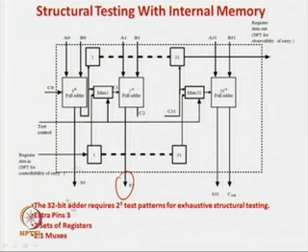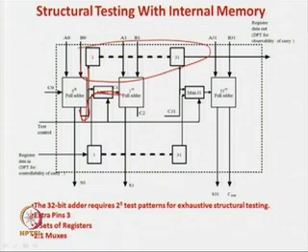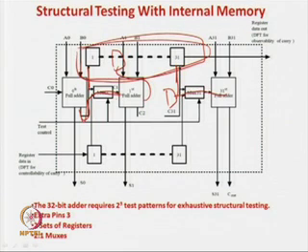In this case people have applied a very simple logic. We have a simple shift register. What do you do? The intermediate carry output of this gate is feeding this. For the time being, forget about the multiplexer, this is being fed to the next level of the adder, and also the same thing is written to a shift register. Again there will be another element of the shift register which will be fed by the output of this gate. Similarly, the output of the second last full adder will go to feed the last full adder, as well as write the 31st shift register element. So, we have a 32 bit shift register here.